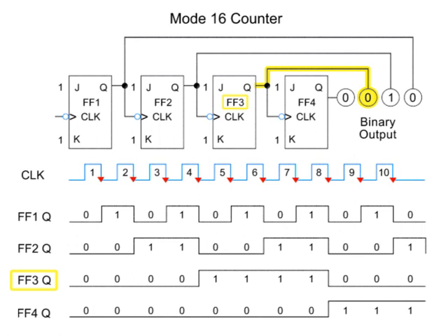The 4's position will change less often than the 2's position, and the 8's position less often than the 4's. Thus, each more significant bit will toggle fewer times. Let's observe how a sequence of 10 clock pulses will ripple through a series of 4 flip-flops in this 4-bit counter.